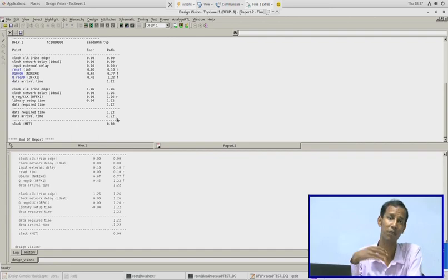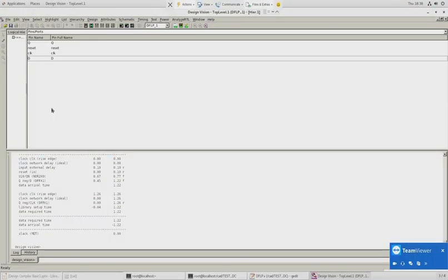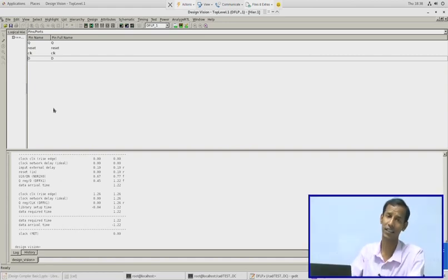So that means the minimum period for the D flip flop that I designed is 1.26. So 1.26 means the frequency of that designed flip flop will be near about 1000 divided by 1.26 megahertz. Okay, so in this way we basically design in a design compiler. So this is just the basic to show you how to start with the basic elements. I have started with the basic elements, adder for a combinatorial circuit, and D flip flop